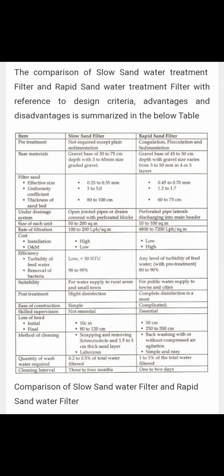The water which comes from the sedimentation process, which removes 60 to 70% of solids, can after that directly enter the filter without the coagulation and flocculation process. So for pre-treatment, only plain sedimentation is required in the case of the slow sand filter.